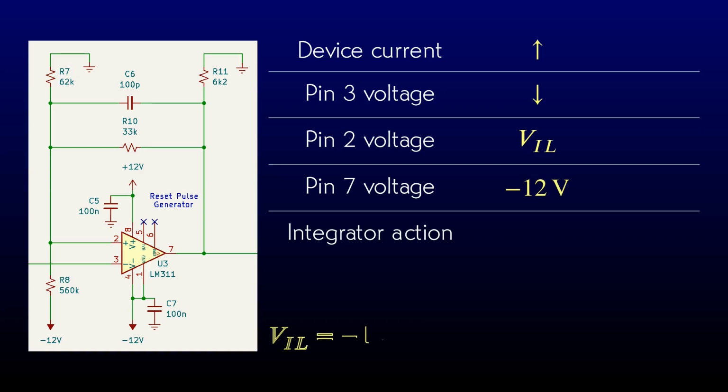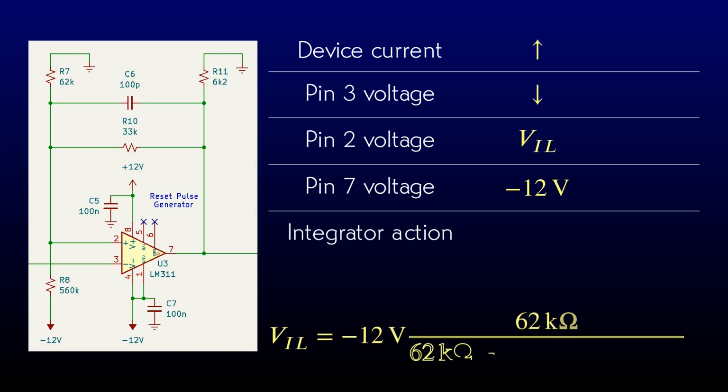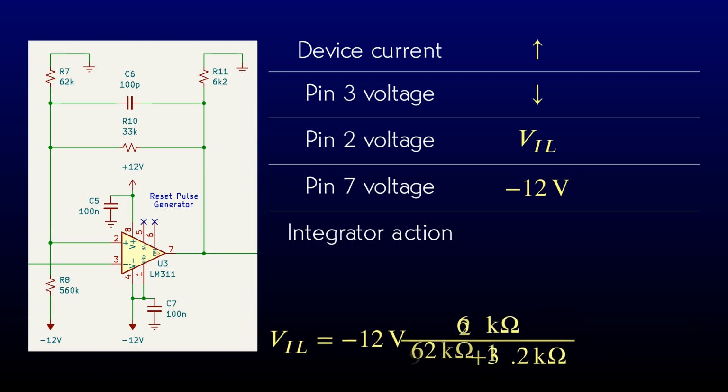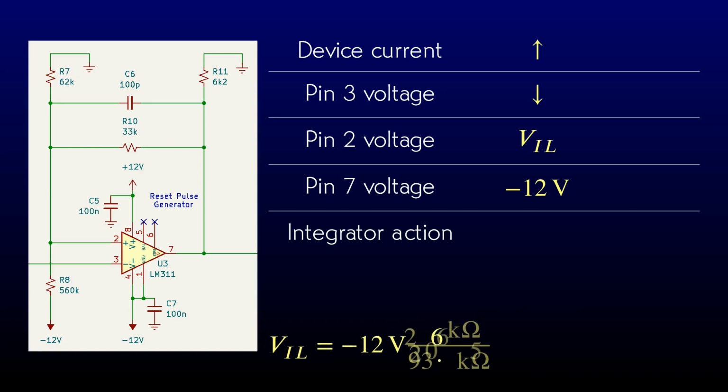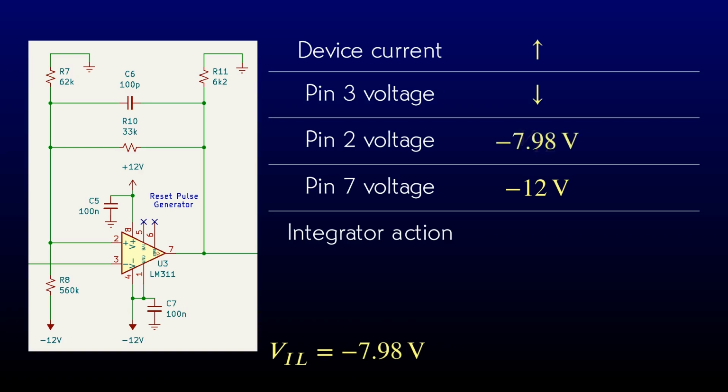The only components carrying DC current are the resistors. By now, we can analyze the network on autopilot. And negative 12 volts on the reset line means that the integrator should integrate.